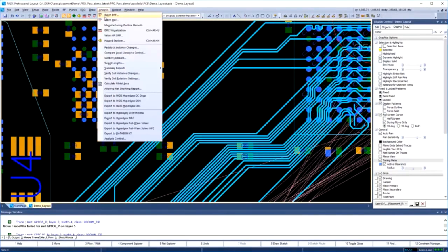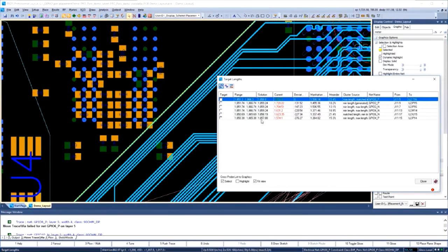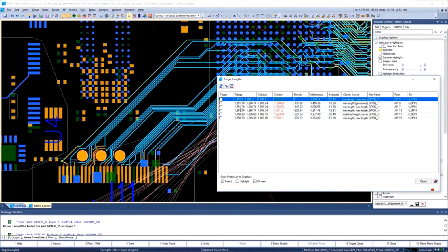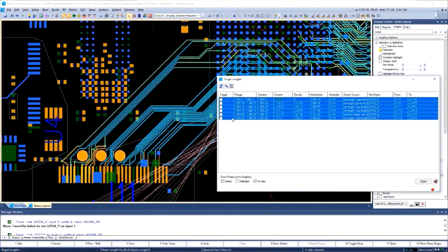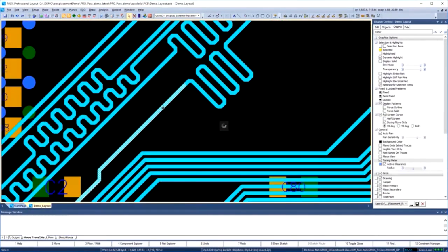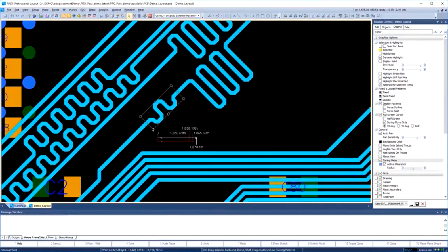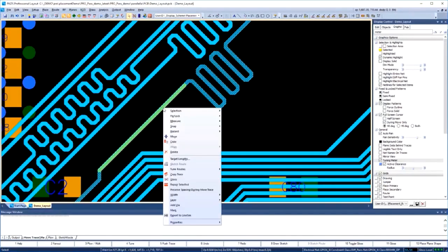With the target length dialog, view constraint-dependent nets by selecting one net. Sort and view the longest net of the bunch to plan your attack. Cross-probe and select your nets of interest for manual tuning, or tune the bunch using auto-tune. Auto-tune uses the constraint definitions, providing a one-button tune that meets electrical delay requirements, enabling you to minimize rework and ensure your design will meet the most stringent timing definitions. Manual tune gives the designer more control to precisely add length to meet the most complex constraint definitions. Open up dense areas of the board to add length to traces where needed, while preserving existing tune structures.